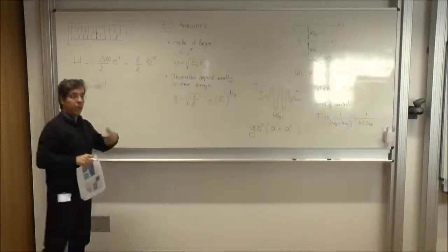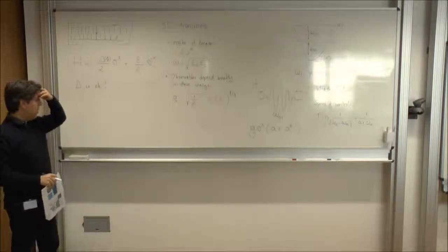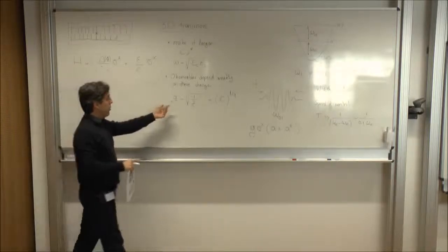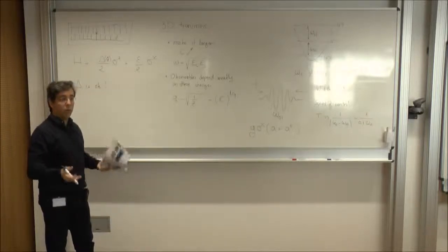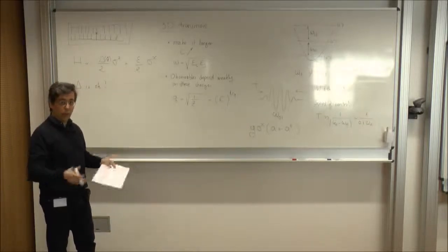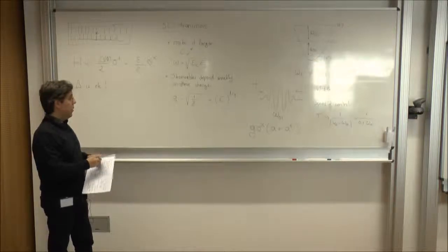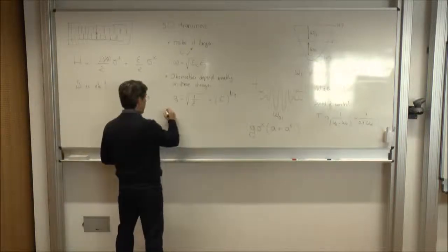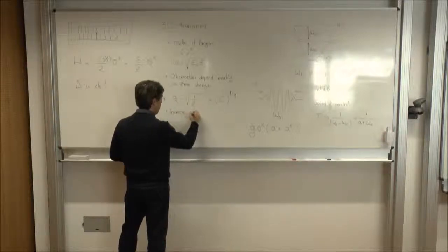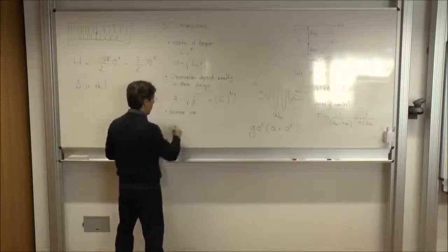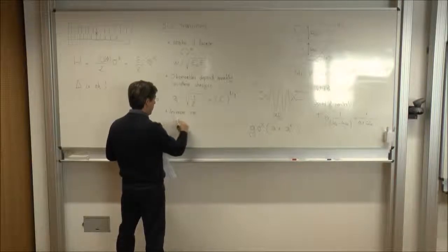So you can change the capacitance of your transmon, but it's not going to lose coupling power because of that. Because the amount of charge that it's going to store, assuming that this works like an oscillator, is going to be very similar. But at the same time, you can increase the size. So you can make a larger dipole.